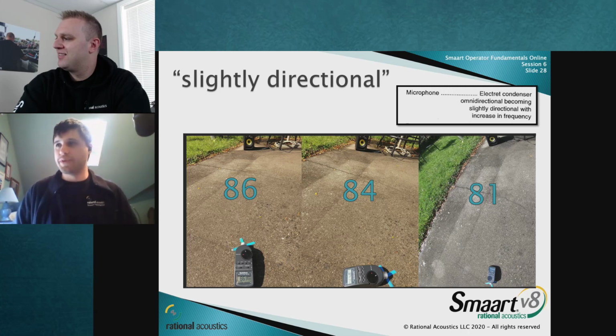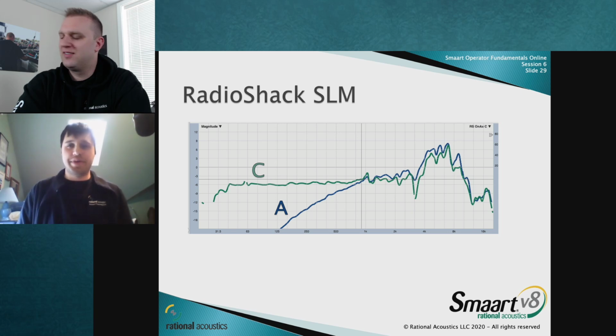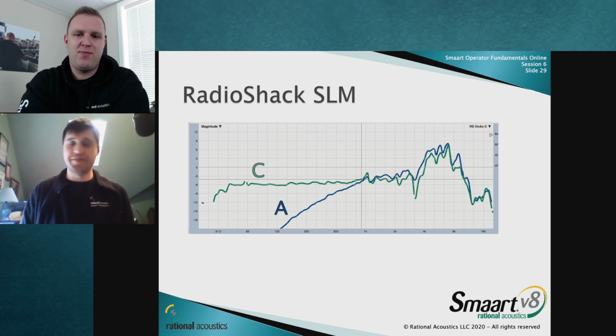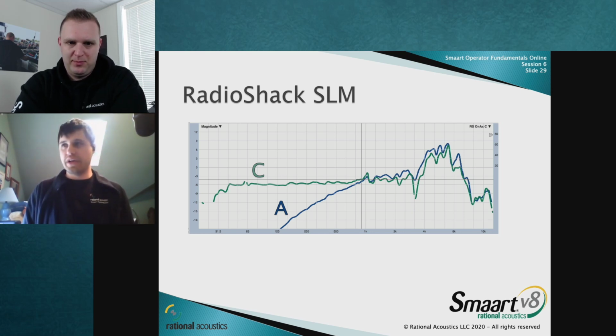If you go to the next slide for me, Chris. Yep. This is the frequency response of the mic capsule that's inside that meter, and with both weighting curves. And you can see it's absolutely not flat. And the reason this is a problem is because your reading is going to change based on the tonal content of the signal that we're measuring.